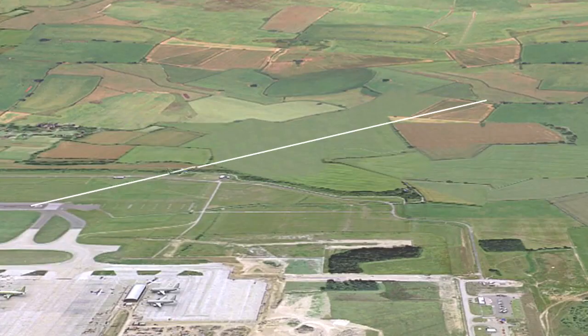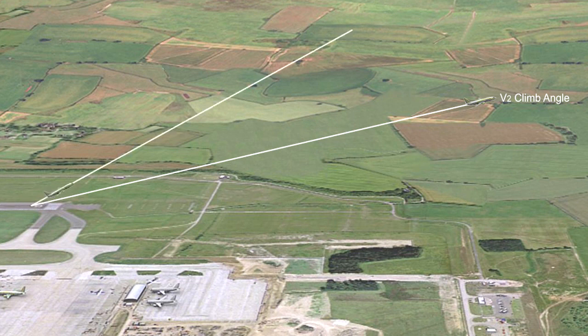Before we start, it is important to understand that in the event of engine failure, the initial climb-out speed is V2. However, V2 is not the best climb angle speed. V2 is considerably slower than the best angle of climb speed, which, if you recall, is called Vx. As an example, for a typical new generation 737, Vx is 80 knots faster than V2.